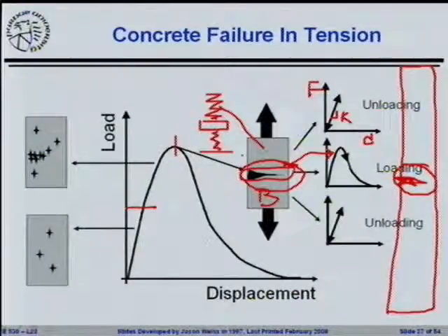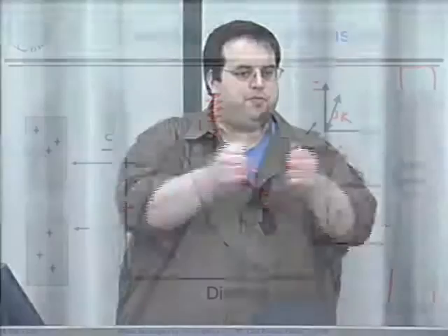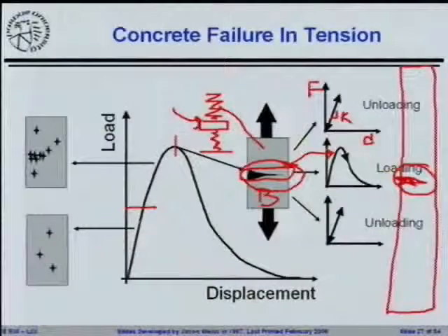In other words, you've got a damaged material in between two great big rubber bands that you are pulling apart. And you all know from playing with a rubber band, you pull that rubber band, you pull that rubber band, you pull that rubber band. When that rubber band snaps, it releases a certain amount of energy. Right? The energy that it's releasing is what's stored. Part of the energy is coming out of this crack, but there's an awful lot that's coming out of the unloading of that spring. So if that rubber band is getting bigger and bigger, there's more energy stored in that entire system that has to be unloaded. Okay, and that's where we really get into big issues.